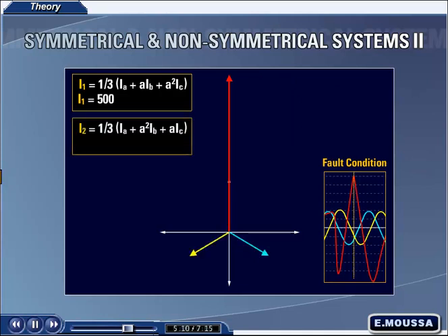The negative sequence formula has an a operator on phase C and an a² operator on phase B. After phase B is rotated 240 degrees, and phase C is rotated 120 degrees, the final position of these phases are known. Adding the 3 vectors reveals that phases B and C combined equate to 1/3 of phase A, however, pointing in the negative direction, requiring them to be subtracted.